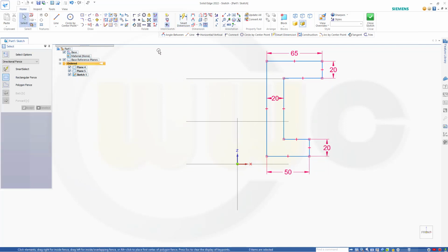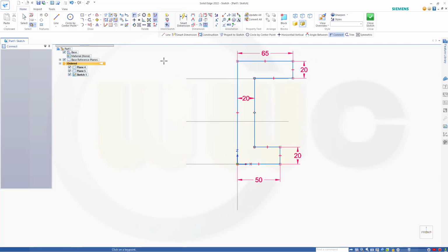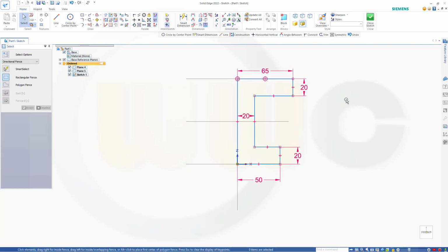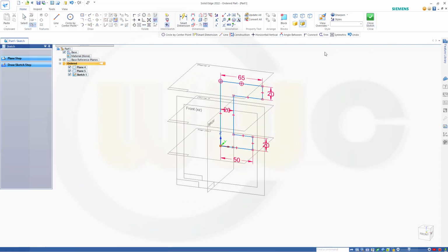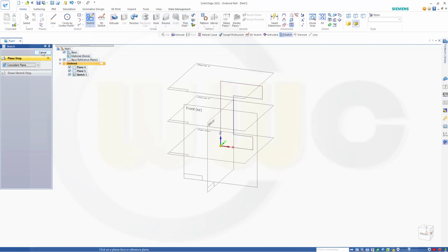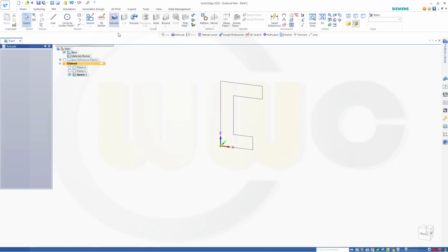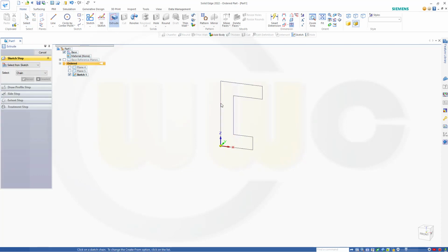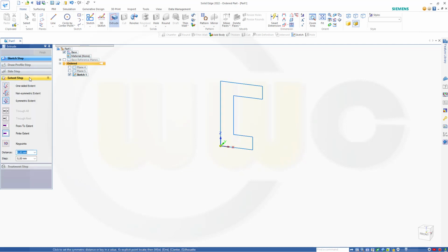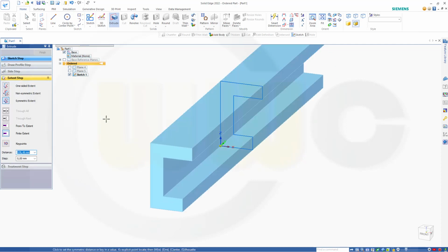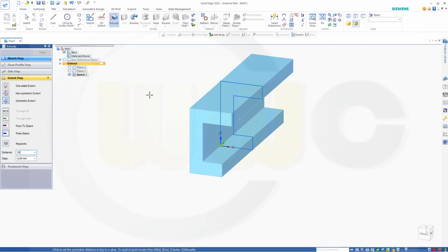Now let's add some constraints. Let's put this point here and that point coincident, and then go for collinear this plane and that line. Should give me a fully defined sketch. Close that sketch, make an extrude, make it symmetric. With the sketch, accept. It should be symmetric, yes, and the distance should be 55.